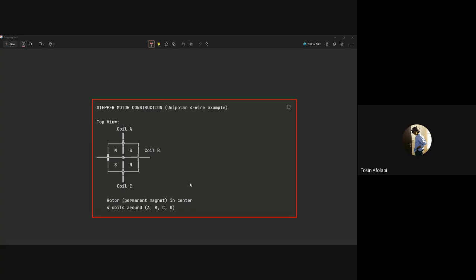So we have the full step. That's 4 steps per cycle. Since we are moving at 1.8 degrees per step, for a 200 step motor, each cycle is moving at 4 steps each. It's simple, but it's less smooth because it's going to create jaggedness and other things like that. It's like watching something at 40 frames per second instead of 60 frames.